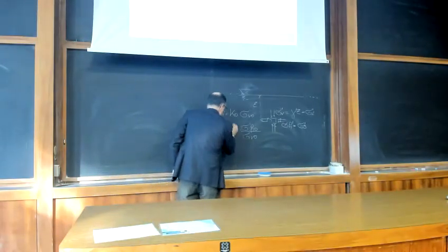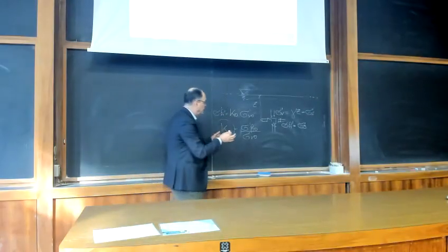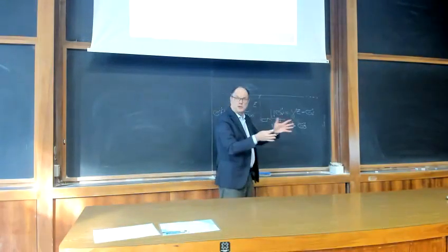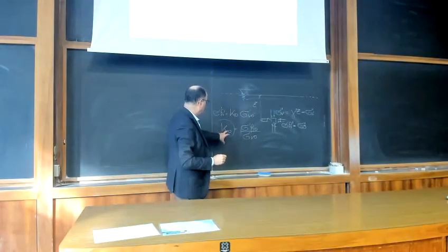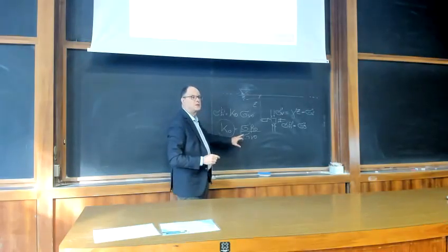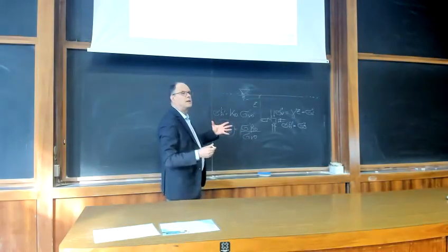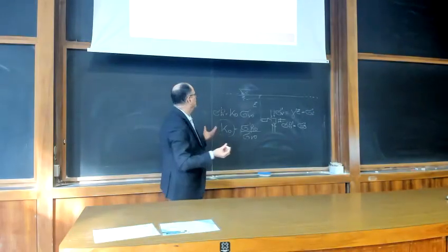Now, this was called earth pressure coefficient because it is something related to earth pressure, which is what we are talking about today. K0 is therefore the ratio between these two stresses, and it is not possible to determine analytically.